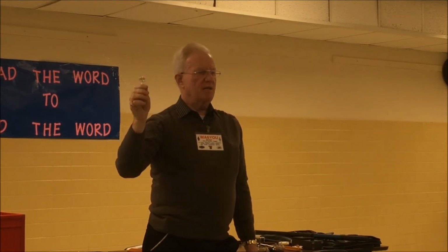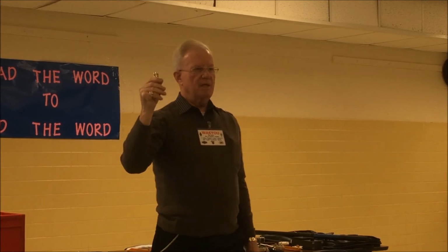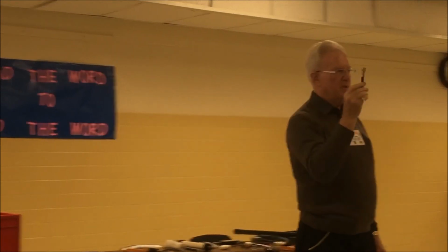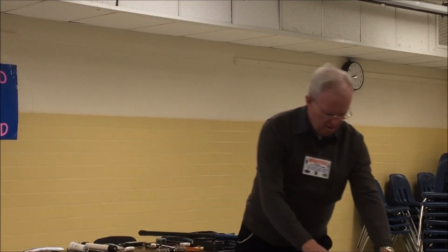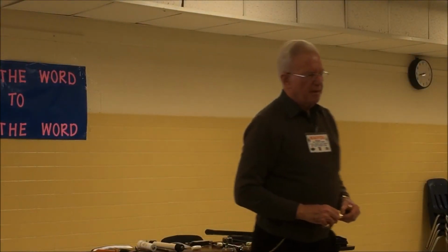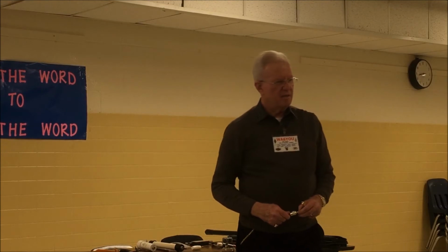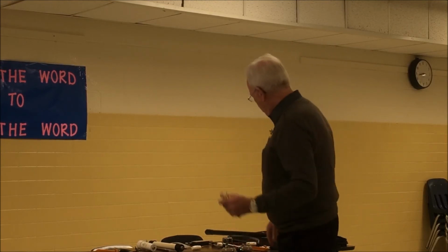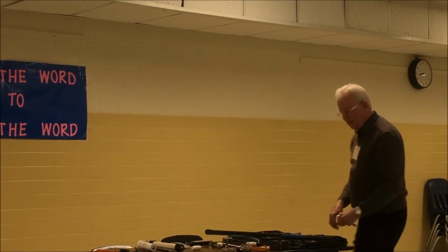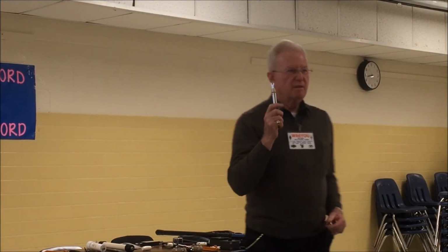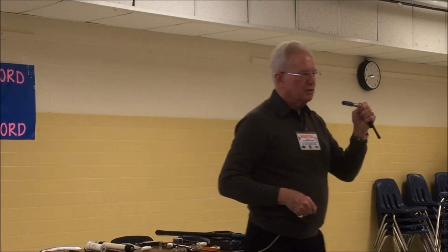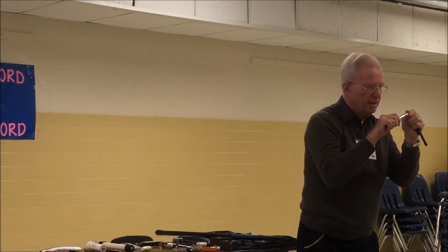This one is a crimp, and I do it all the time in class. I have my students time me. I can put one on in 90 seconds, full mil spec. Why don't you like SMA? Too small, problematic. Students break the pins, they cross-thread them, and by the way, what's the torque on an SMA? 8 inch-pounds. I got a torque tool just for SMAs.